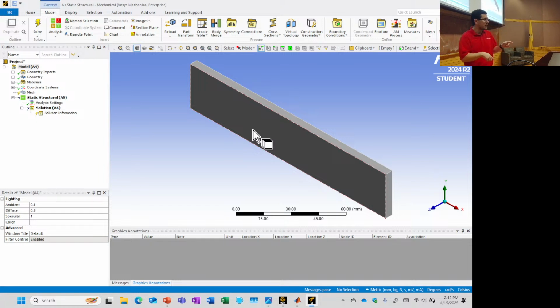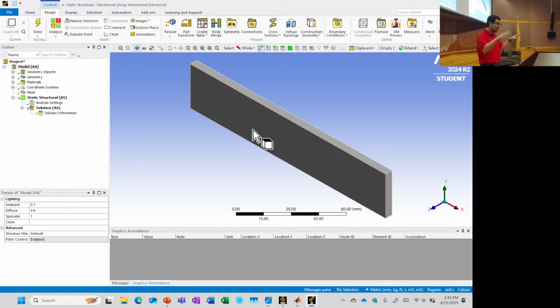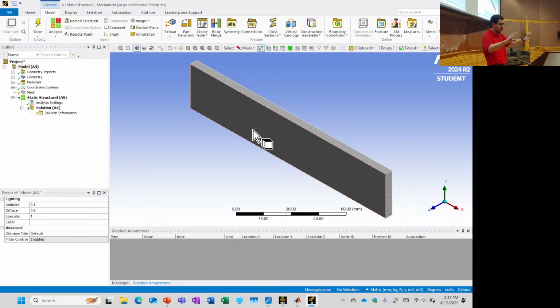Okay? Yes? How does ANSYS solve this problem? Okay, so what it's doing right now is the finite element, straight up. I can talk about mechanics. What it's going to do instead, when we get to buckling, is actually solve an eigenvalue problem. And this is what it does for vibration as well. Impressionist perspective, but essentially it's going to be calculating out eigenvalues.